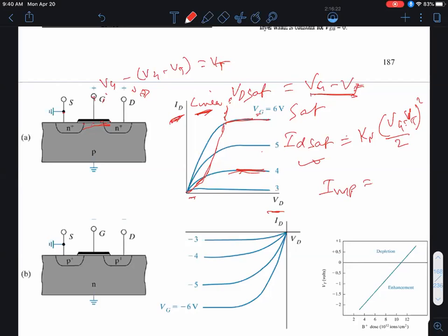is defined by change of voltage divided by change of current, right? Impedance is the general form of resistance, if it's frequency dependent, okay? Let's call this resistance, output resistance. That's change of voltage divided by change of current. Well, I have a certain change of output voltage. What is my change of current? 0. Therefore, the output impedance is infinity, right?